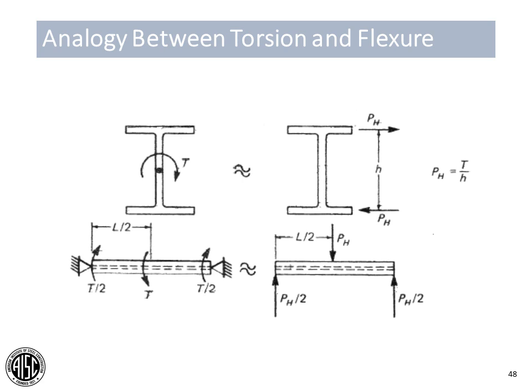So here's that analogy. You have torsion on your runway member. This is approximately equal to the moment couple forces acting on your top and bottom flanges. You then would take this horizontal force and apply it to the top flange, or top flange and a portion of the web, and analyze that portion of the beam as a simply supported beam in flexure.